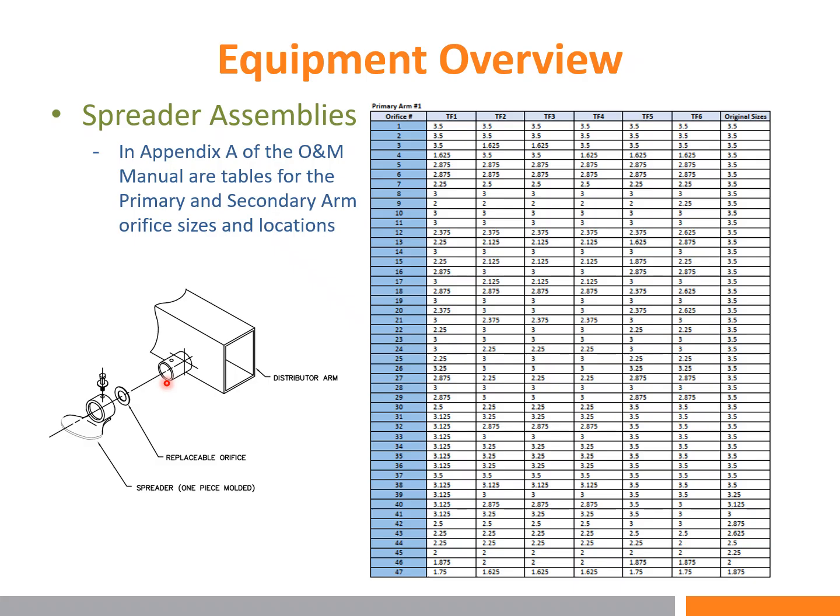However, if you see other numbers, for example, we'll look at the discharge port which would have an orifice size for trickling filter 1 at 2 3/8, that means the diameter of the hole for that particular orifice at that location is 2 3/8 inch diameter.